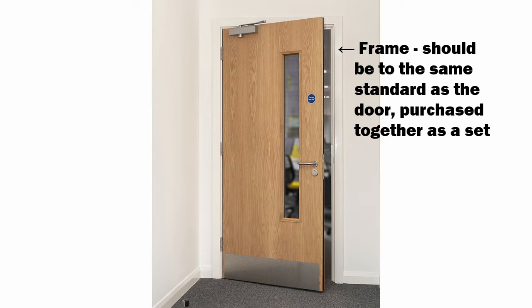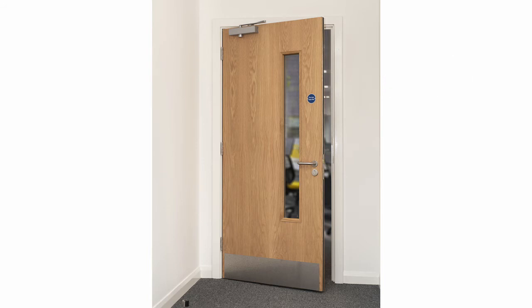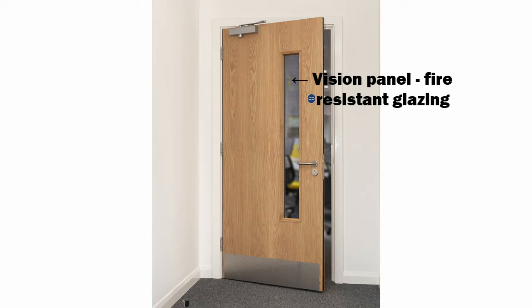Every fire door is therefore required to act as a barrier to the passage of smoke and/or fire to varying degrees depending on its location in a building and the fire hazards associated with that building. The main categories of fire doors are FD30 and FD60, which offer 30 and 60 minutes fire protection respectively. Manufacturers can certify fire door sets both for identification purposes and to guarantee their performance in a fire situation.